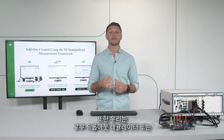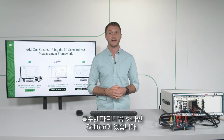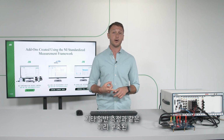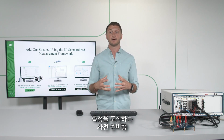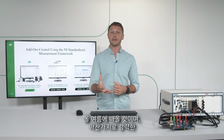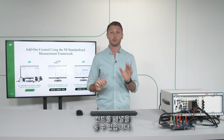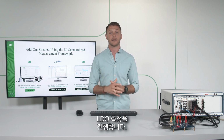Now, we also have Soliton, one of our specialty partners, developing our first DUT-specific measurement suite, and that's for a low dropout regulator, or LDO. This is going to be a canned solution that includes pre-built measurements for common things like line and load regulation, line and load transient, power supply rejection ratio, and other common measurements that are needed for validating an LDO. Now, that's coming this summer, and it will, again, follow that same really powerful workflow. And you can even mix these together so you can have the semiconductor device control panel right next to your LDO panel. So you're controlling the registers and doing the LDO measurements in the same experience and the same workflow.